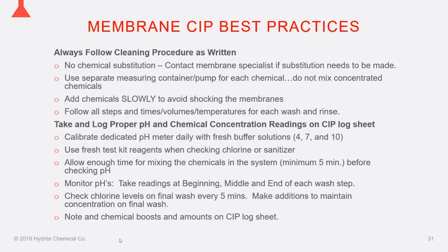So if you go and take a sample for your pH checks or your chemical titration checks out of the concentrate sample port, which is very common, that is at the end of the system where each of the stages upstream have removed some water. So ideally, you could be getting a sample that you're checking that's going to be more concentrated than the average in the system because you've removed that water.